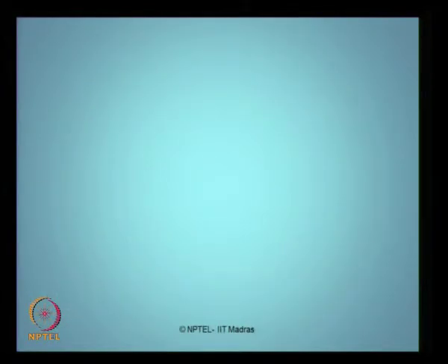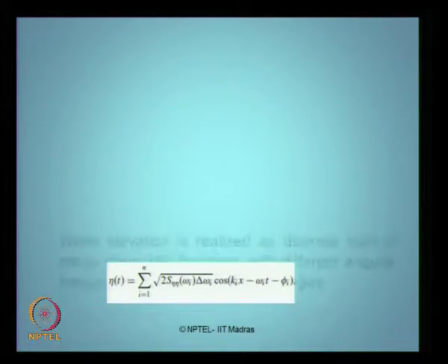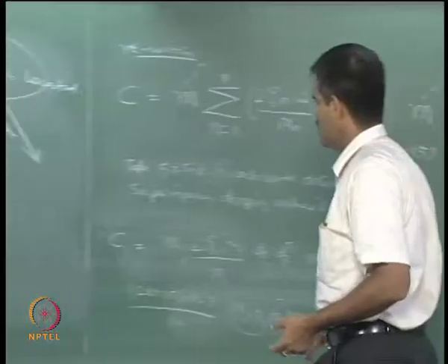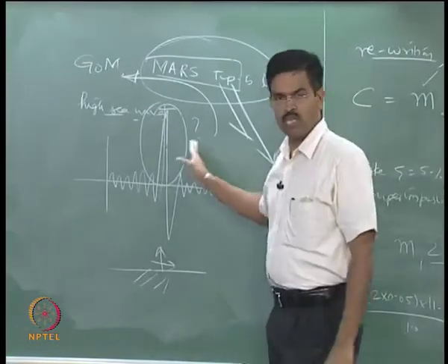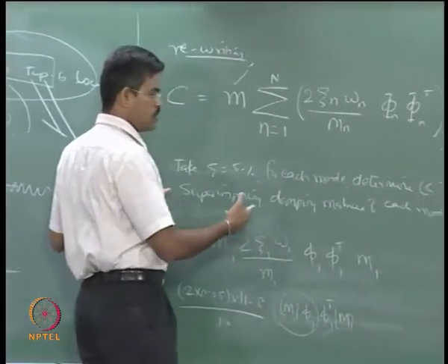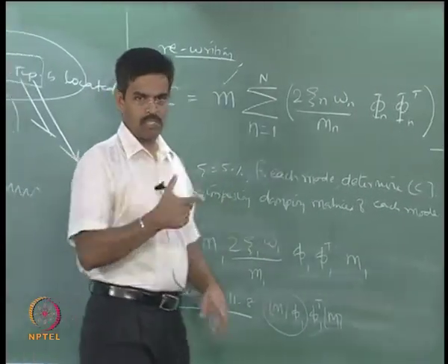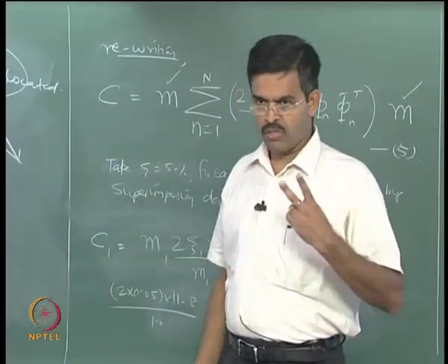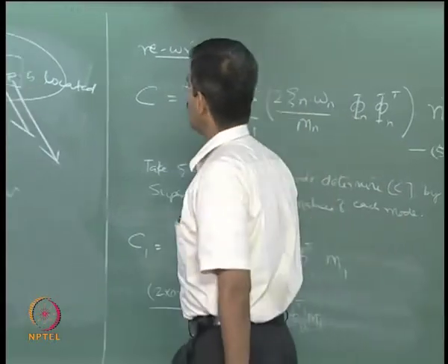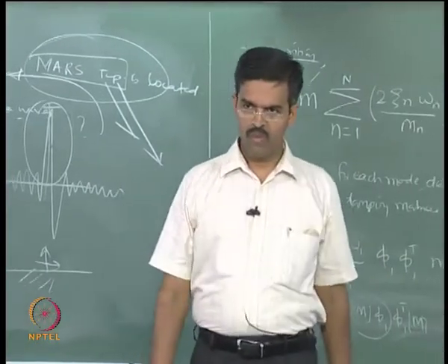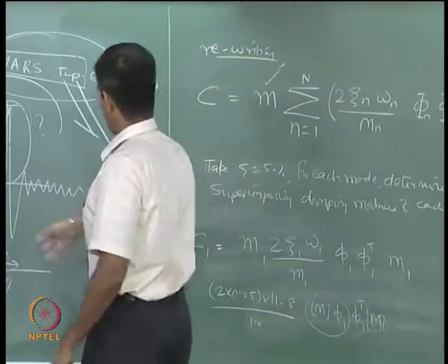So, once I do this, I generate a wave and pick up the sea surface elevation of the wave, because I want to plot the time history. Why am I plotting the time history, you may wonder, when you have a spectrum, from the spectrum we can directly do an analysis. Okay. You remember I am using Rayleigh damping, the Rayleigh damping said I must use unconditional convergence, I must use a time stepping procedure. Okay. So, I want to convert this into the time domain for two reasons, one is for this, and two, I want to be sure that the wave generated is steep and asymmetric. Okay. So, I must generate a wave of this specific order.